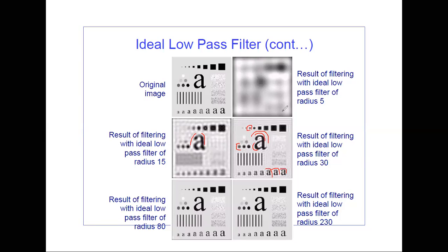Remember, in DSP we studied this rectangular window. Why is the rectangular window bad? Because the sudden transition in the rectangular window would cause the peak overshoots and undershoots. Remember, that was the issue with the rectangular window, the Gibbs phenomenon. We can see it here literally.